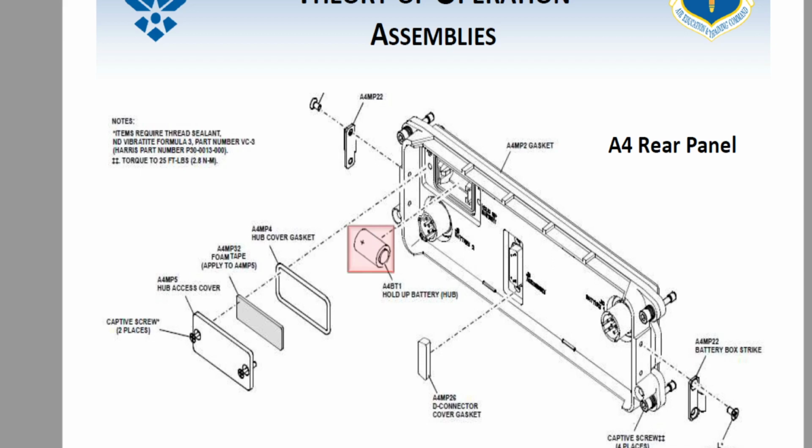Now, one of the things you do want to do is when you store this radio for long periods of time, or you're not using it for a mission, or any radio really, if you're going to be storing them in cold storage, where it's not actively being used, and the only time you're taking it out is to maybe blow some dust off of it because a PMI says to do that, you're going to remove this hub battery, and you will remove any other batteries as well.